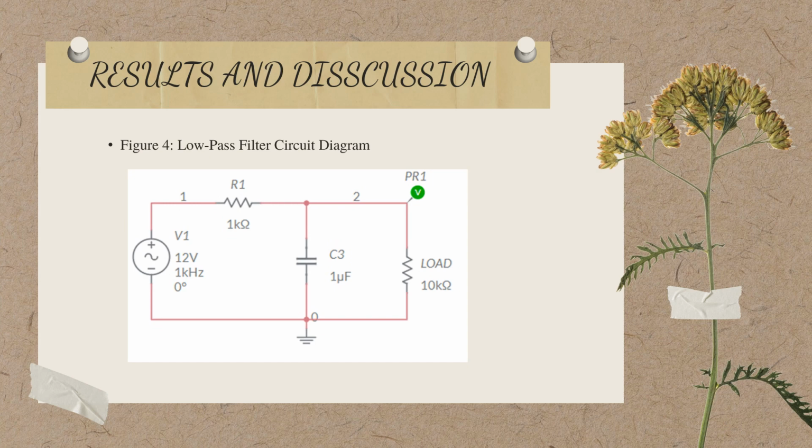Meanwhile, the 1K ohm resistor R1 and 1 nanofarad capacitor C1 at the middle of the RC bandpass filter circuit, figure 2, are the components of the low-pass filter. A low-pass filter is a circuit that offers an easy passage to low-frequency signals and difficult passage to high-frequency signals. The capacitor impedance decreases with the increasing of frequency. The load impedance in parallel with the load resistance tends to short out high-frequency signals, dropping most of the voltage across its resistor R.